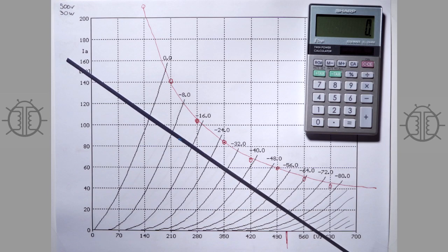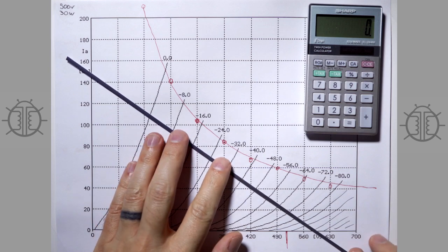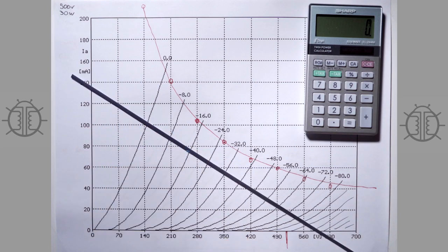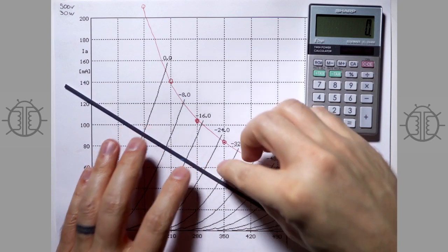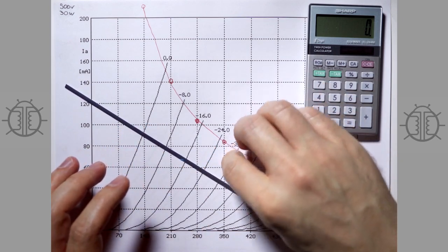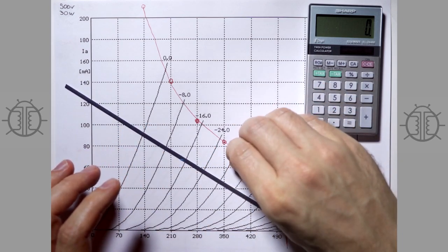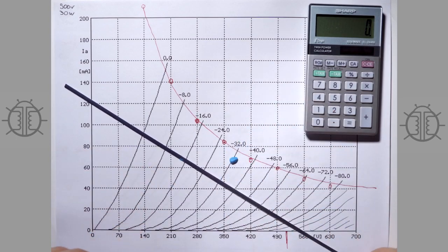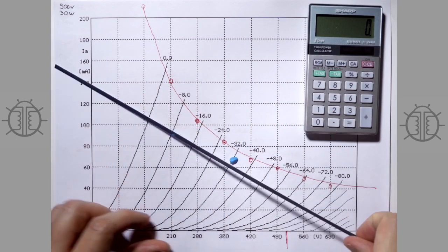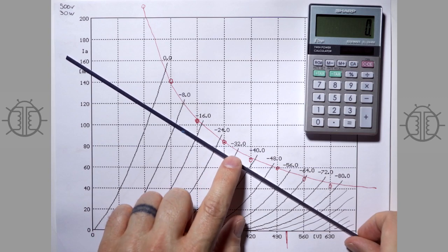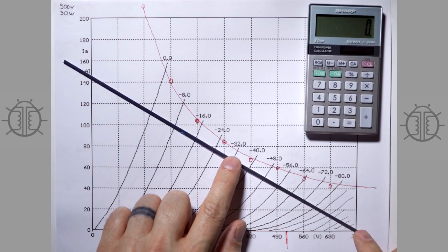And so in this case, we're doing a single-ended Class A amplifier here. And so the output transformer might be, for instance, well, let's just see what it is. Let's pick an operating point. We'll just say it's here with a Class A operating point. You want to bias it close to maximum dissipation, and you want to swing through as much voltage and current as you can.